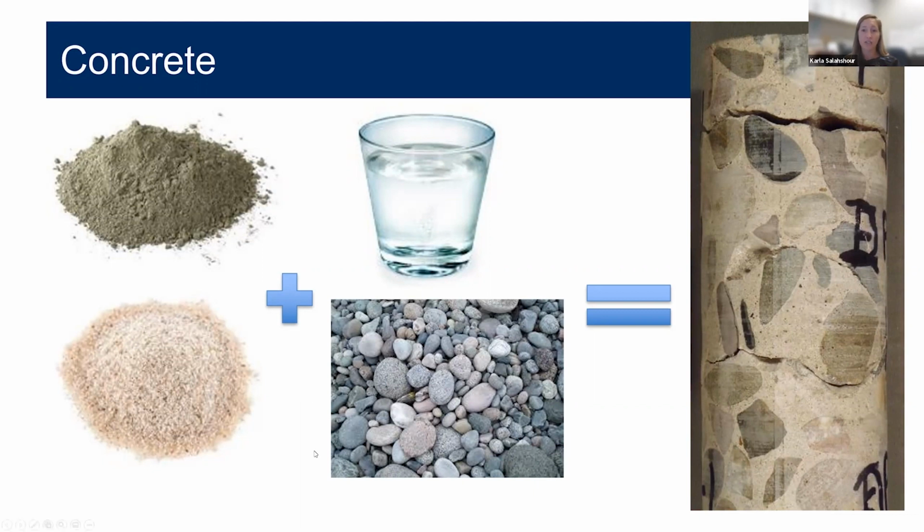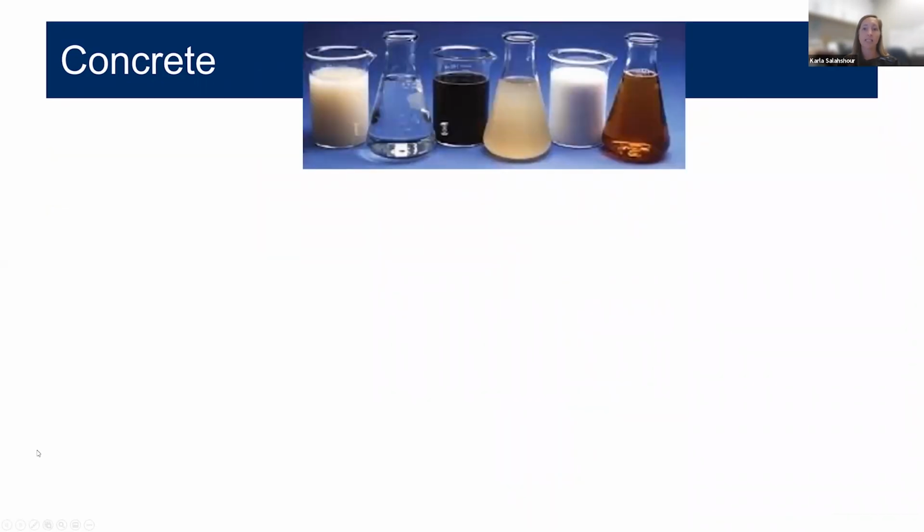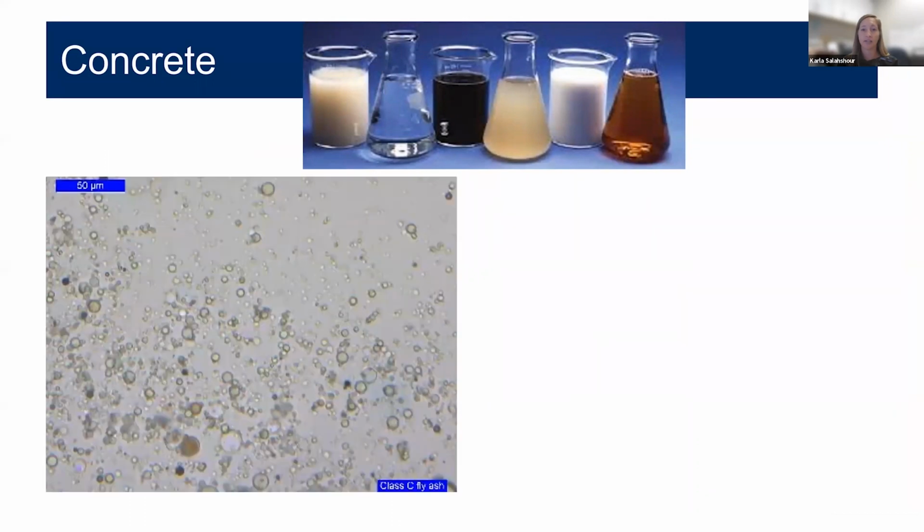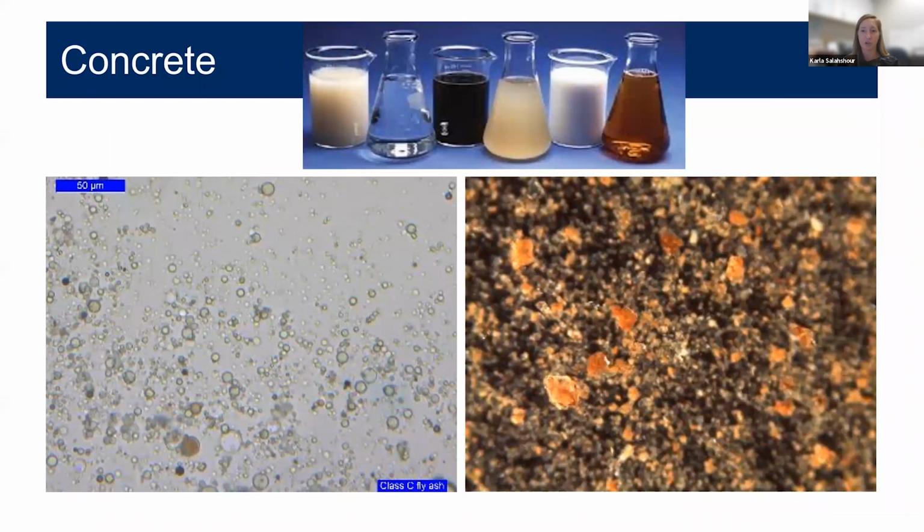So we're also seeing the use of many different types of these materials like admixtures and supplementary cementitious materials like fly ash, and even other types of cement like high alumina cement shown here. And so because of these changes over time to these raw materials, we're occasionally able to provide a range or an idea of the time frame of construction for the material that's being examined. But I caution that this is not always the case in a petrographic examination.